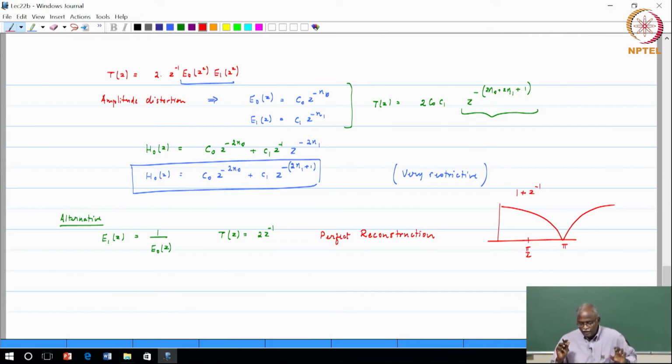Now, if I do not do any processing, I will be able to recombine and get it back, but the minute I do any quantization or something, then the reconstruction will be a mess, because a lot of aliasing has crept in. Now, that is where the problem lies. I should come up with a system where even if I have done some processing, I should be able to reconstruct with a fair amount of fidelity, right. So, that is why I do not want to introduce a lot of aliasing in the signals to begin with.